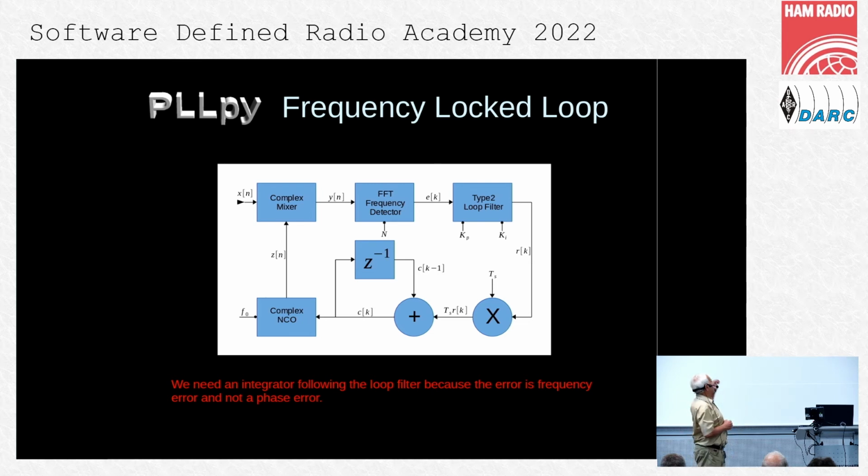And that's why we used this frequency lock loop for the initial lock. When the frequency was locked, okay, we switched off the frequency loop and held the output control signals and switched on the phase lock loop. And after that, it will lock for the phase very fast.